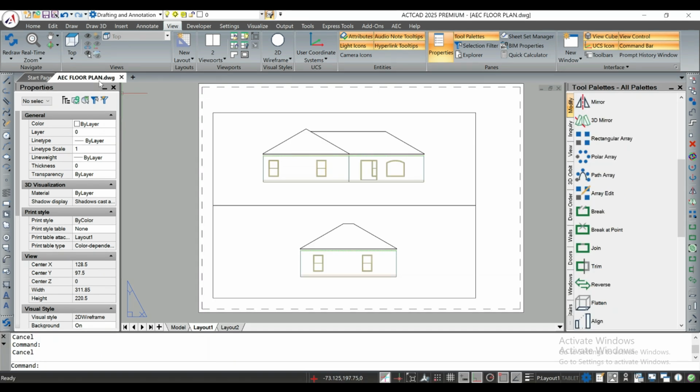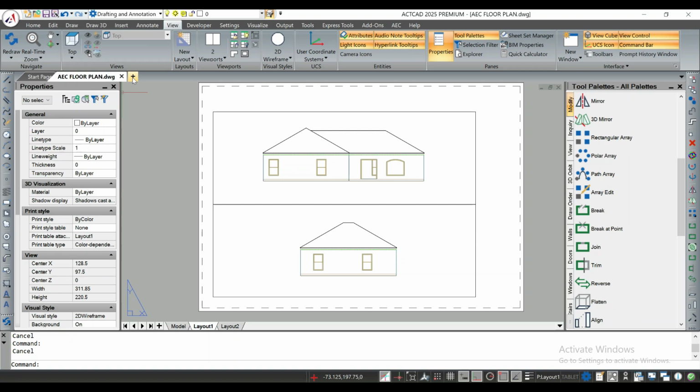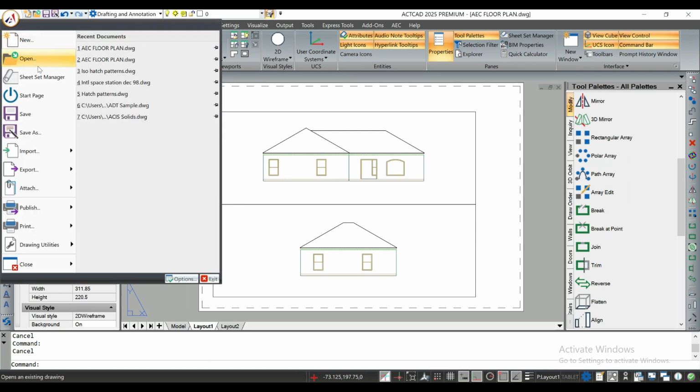Of course, I'm not producing production drawings. I'm just showing the process for generating sections and elevations. In the real world, I'd have callouts, view labels, and various dimensions and annotations. Our last step is to create a PDF of our layouts. But this time, instead of using the print command for each, we'll do them both at the same time with the publish command. I'll start it from the publish flyout in the application menu.